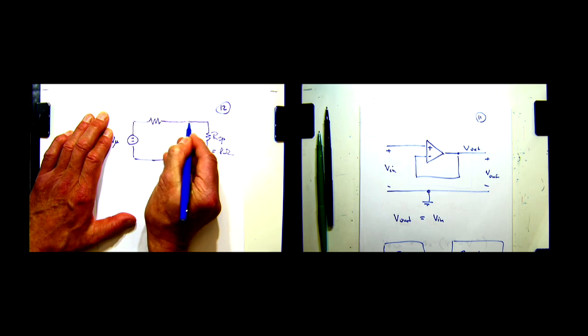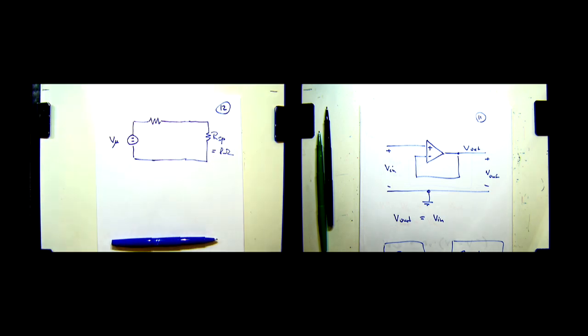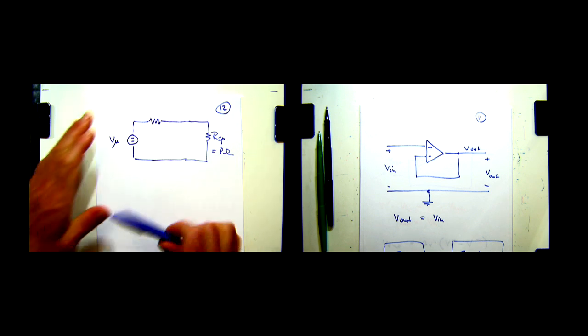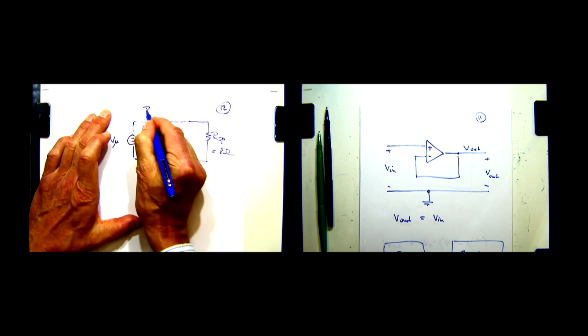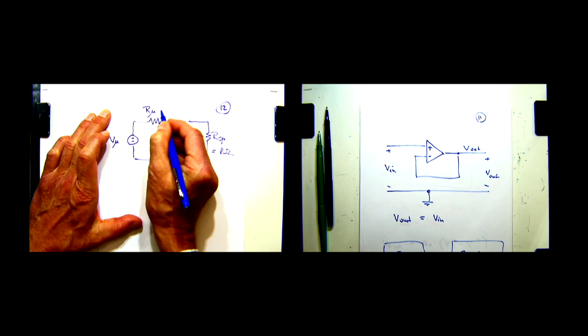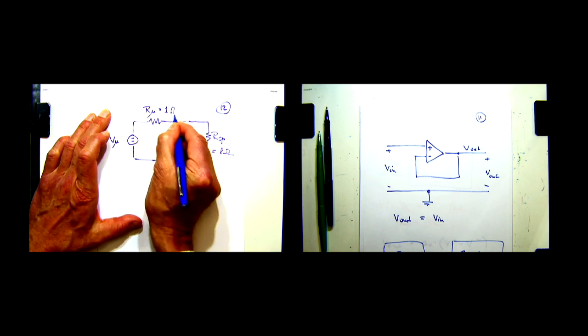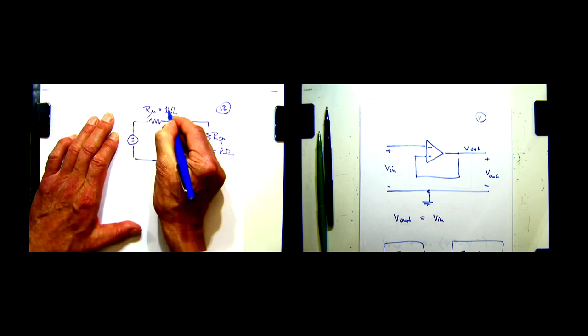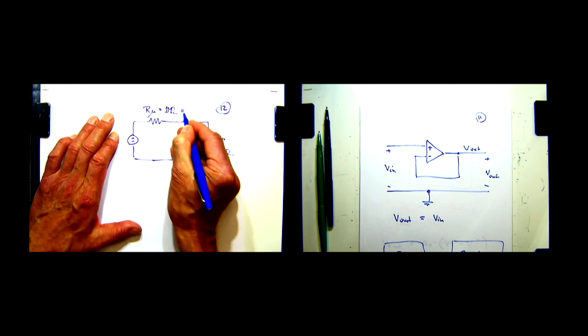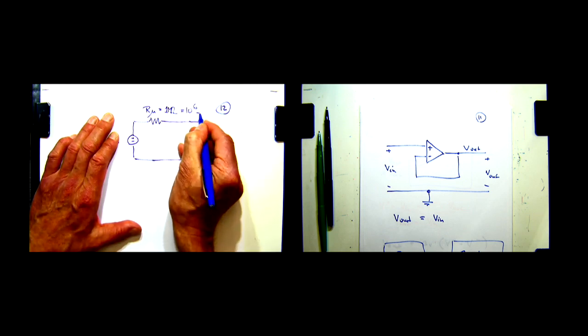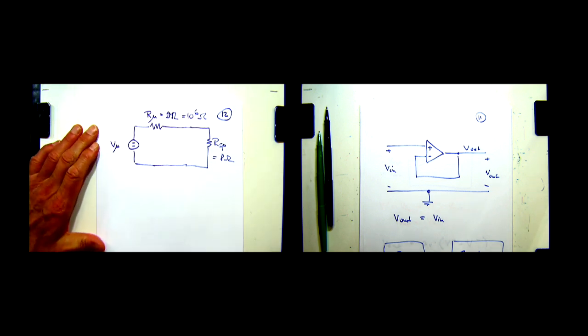So, our microphone is not an ideal voltage source, but we can model it as an ideal voltage source with an output resistance of, let's say, something like 1 megohm. So, in other words, 10 to the 6th ohm. Okay? That would be a reasonable model for our microphone.